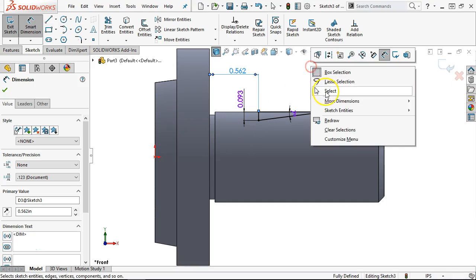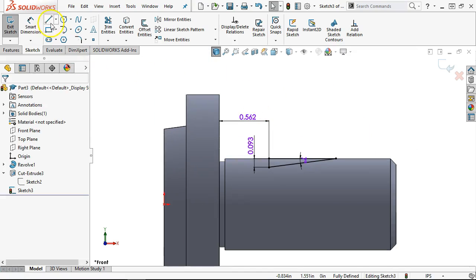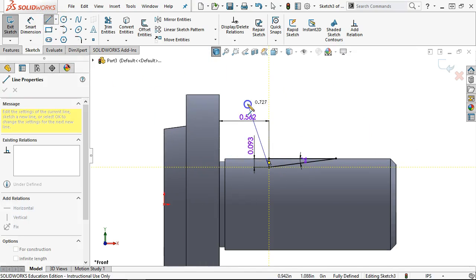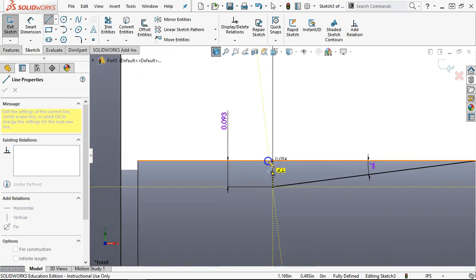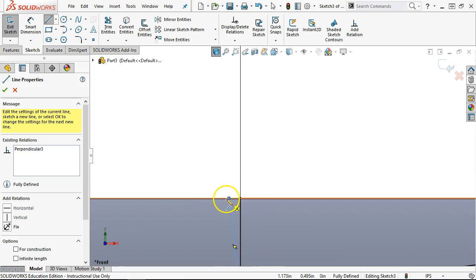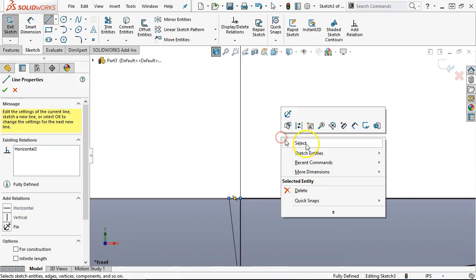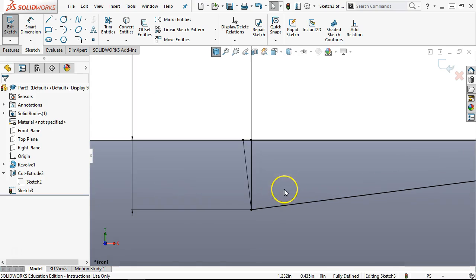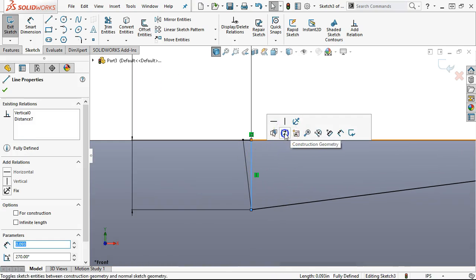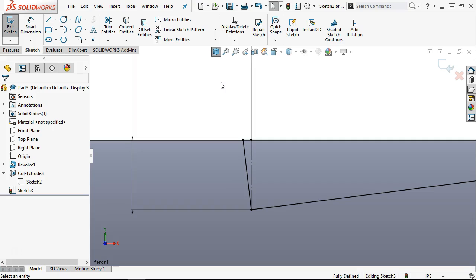And the issue here is still the manufacturer. I guess the one that I would be most interested in is if I come off perpendicular, do I have enough clearance to bring that end mill in? All right, so there's perpendicularity. It does. And then we close off the end. And the choice then is to stay with the contour and region or convert to construction geometry.